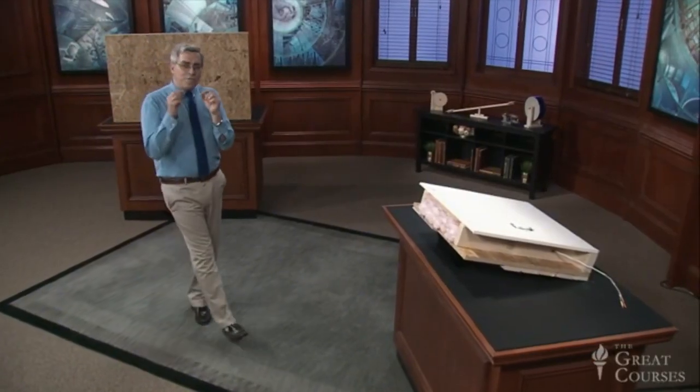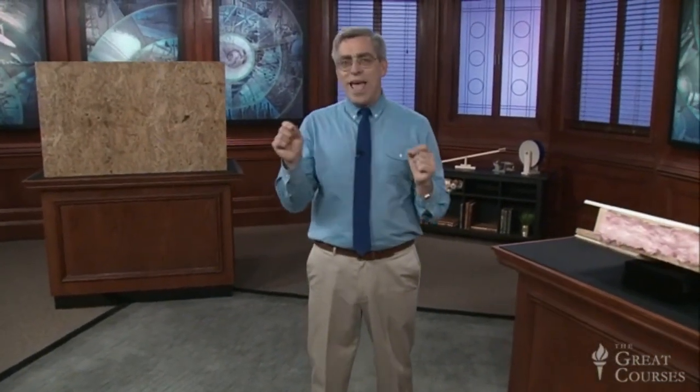I'll conclude with just a few words about our final two basics of energy efficiency. First, energy efficient HVAC equipment. In the last lecture, we discussed many aspects of efficiency in heating and air conditioning systems, but we didn't discuss the most important factor, getting the size right. HVAC systems can waste a lot of energy if they have too little capacity or too much capacity.